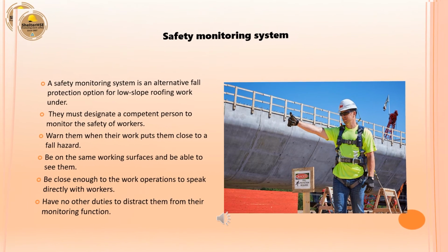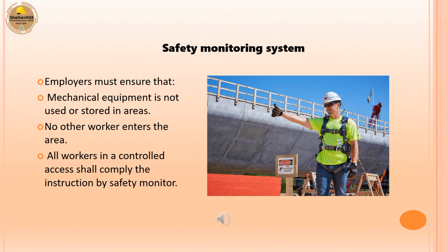Employers must ensure that mechanical equipment is not used or stored in the area, and that no other worker enters the area. All workers in a controlled access zone shall comply with the instructions of the safety monitor.